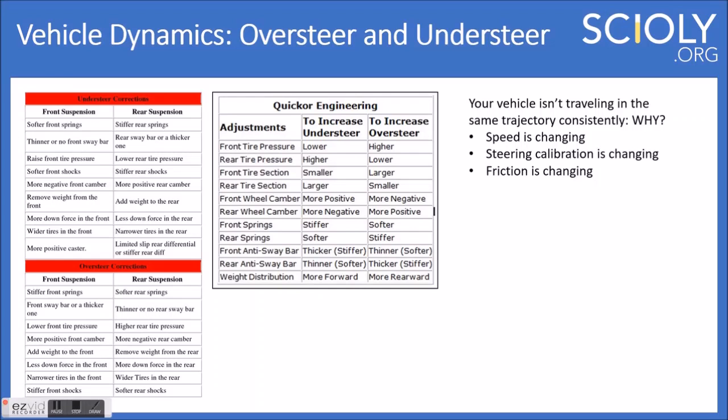And so say the first run, immediately after applying the belt conditioner and cleaning the floor, we would see it end up 13 centimeters to the left of the target. And then we'd run it again, exactly the same, we didn't change anything. We didn't apply belt conditioner a second time because the wheels were sort of kind of grippy. And we would see it end up maybe 1 centimeter to the left compared to 13. So it would just shift like 10 to 12 centimeters just due to changing the friction coefficients of those wheels. So they had huge impacts when you're going at those high speeds.